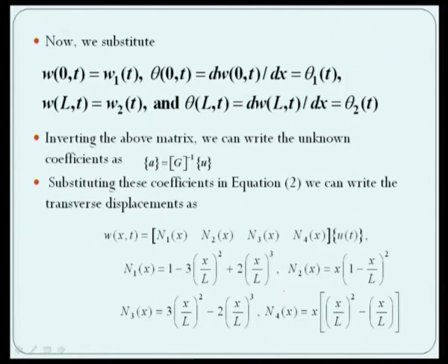So, let us look at this shape function. Does it satisfy the shape function properties? That is, we need that it takes a value of 1 where it is evaluated. Suppose we substitute x equal to 0, we expect that n1 should go to value 1 and all others should go to 0.